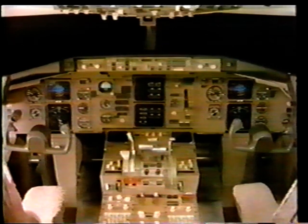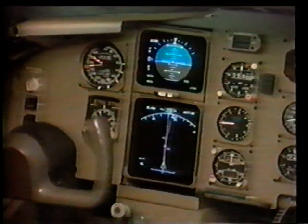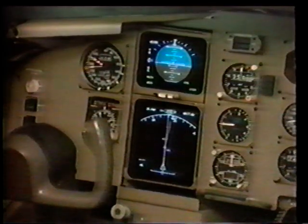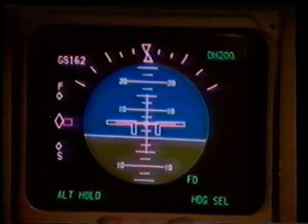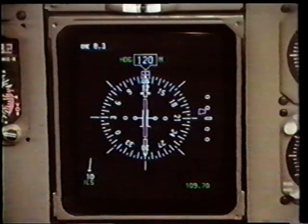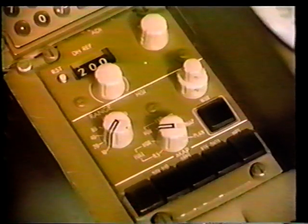This program will introduce you to the 757 EFIS, the Electronic Flight Instrument System. EFIS has been designed to simplify cross-check requirements during all phases of flight by consolidating reference items on single-source instrument displays. EFIS includes the Electronic Attitude Director Indicator, EADI, the Electronic Horizontal Situation Indicator, EHSI, the symbol generators to drive the indicators, and the associated control panels for these instruments.